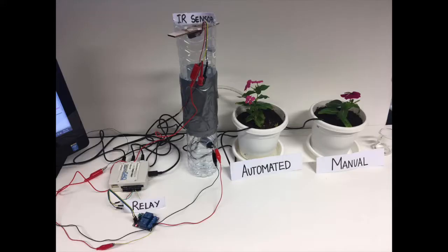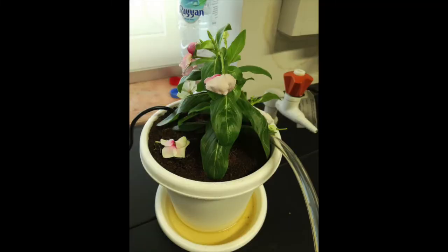The experiment has been carried out for 3 weeks. The first week we spent testing the functionality and parameters of our experimental setups. On the 5th day, we encountered a problem. We observed that after a period of time, all sensors went to zero, causing the solenoid valve to open and continuously pump out water. To save the plants, we added a safety measure which stopped the VI when values went to zero, and fixed the error by restarting the system.